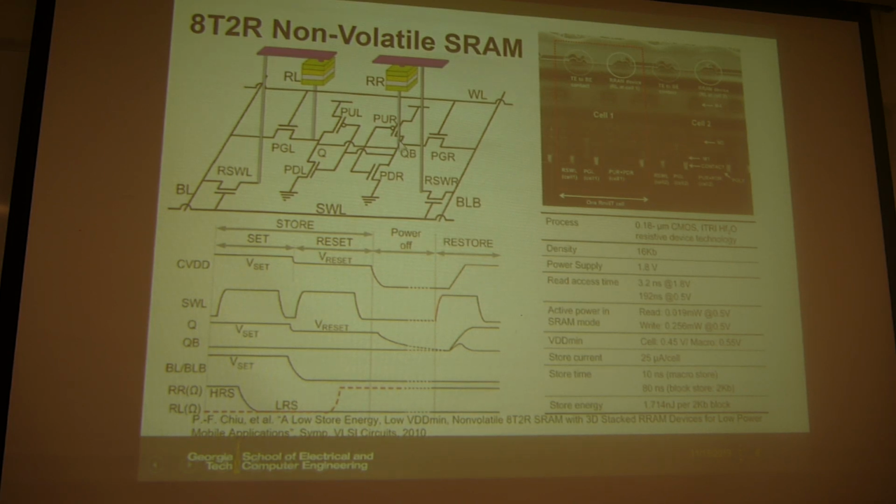So here you see the traditional 6T is here. And then at the Q and the Q bar, those two storage nodes, you have a resistor, or let's say the RRAM stack, in the back end of the line through some higher level metal. For example, in this image, you can see it's some higher metal level here. And your transistors for the SRAM are done on the substrate. So here you have two resistors like this, and then of course you have some contact wire connecting to another transistor, and you have an additional wire line to control those two. So then how does this work?